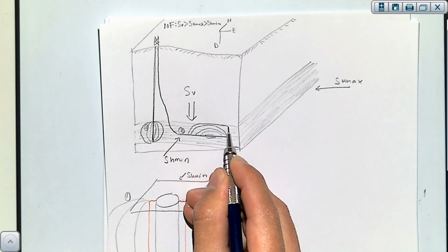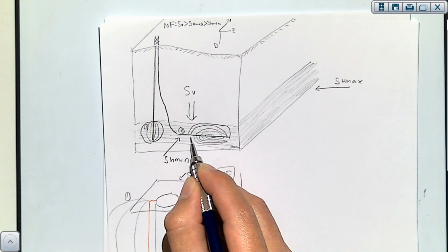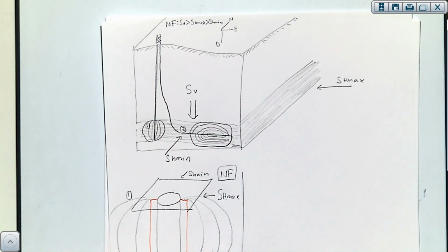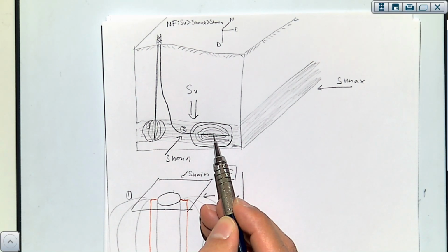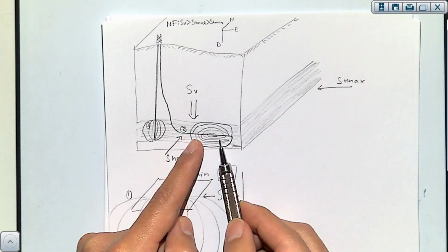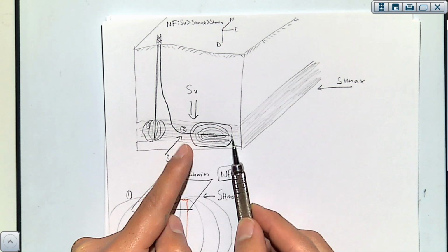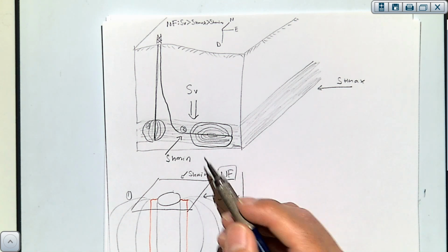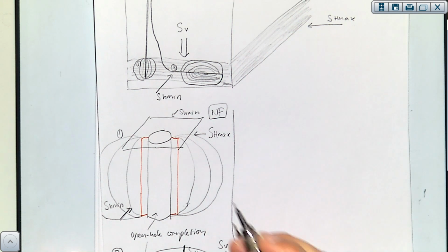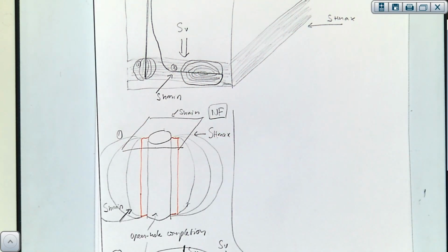And let's assume that the height is limited by the pay into a hydraulic fracture, which is perpendicular, and it is in this location. And even if you have several perforations, and if you have fractures starting at different points, eventually this all will just join in one large plane, because all these small fractures are going to be aligned and later just going to coalesce in the same plane.